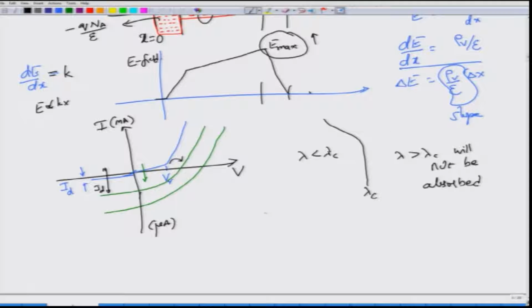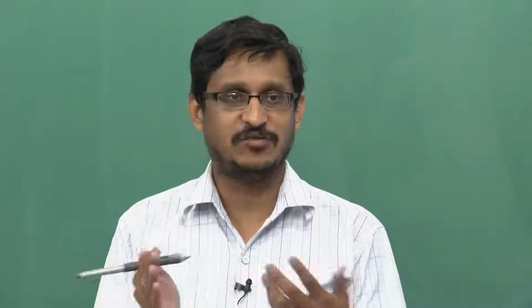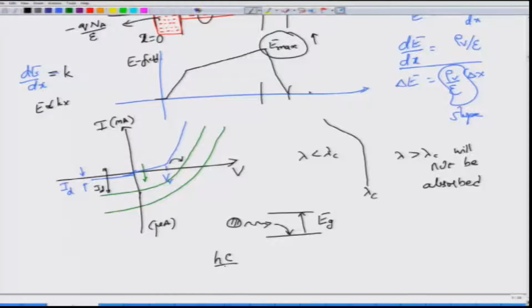Why is this? Well, it turns out that if you go to the quantum mechanics of the materials, what is happening is that a photon comes in and falls onto the photodiode, then it gets absorbed by the atoms in the ground state, thereby promoting an electron of a particular atom onto the upper state. This can happen only when the light energy is greater than the energy band gap available. So if it is less, then you will not be able to absorb; it will simply be transmitted. Then we say that this particular material is transparent. A material is transparent when light cannot be absorbed, right. So you want hc by lambda, which is the energy, c by lambda is f, so hc by lambda is the energy.